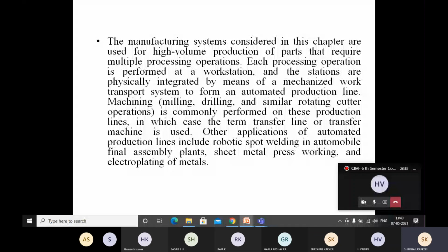So what happens is the work will be jammed in between the A and B stations, because the production rate of the A machine is more than the production rate of the B machine. In such cases, we will be using a buffer storage. The buffer storage unit will be storing the extra material coming from the A workstation. Why is this buffer storage required?